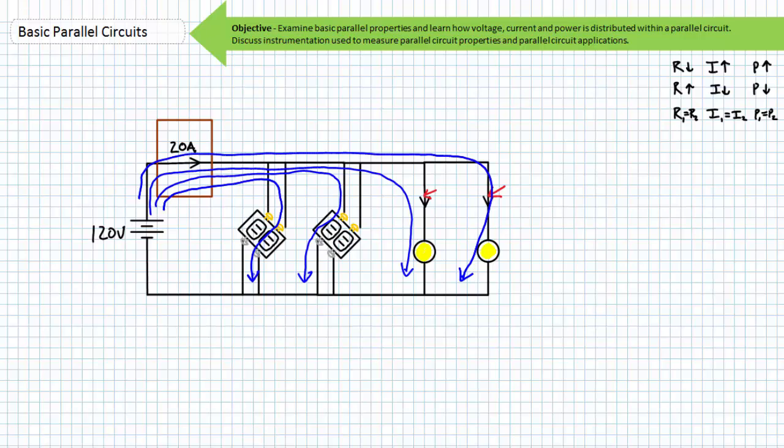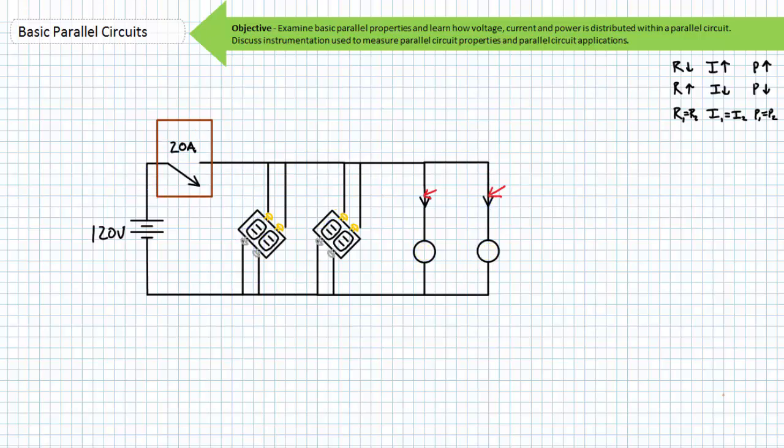At some point, that last hairdryer, microwave, radio, electric blanket, blender, computer, fan, heater, or lamp is going to draw current in excess of the maximum permissible 20 amps from the source. And the circuit breaker will open, and the whole room will go dark because you dropped the total resistance of that room too low and the current to that branch circuit went too high.